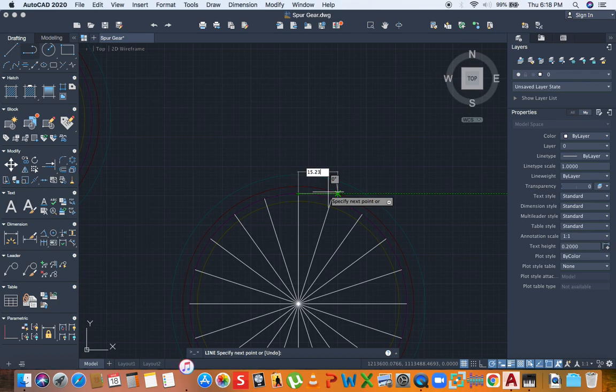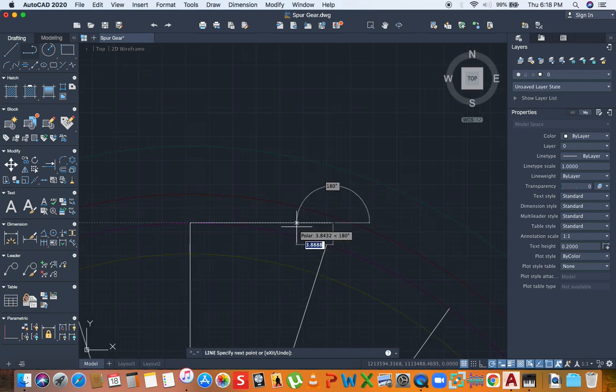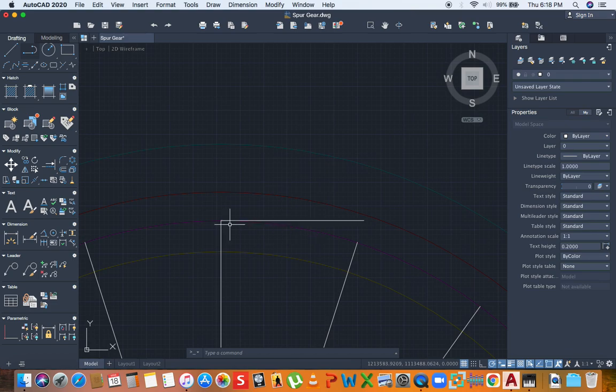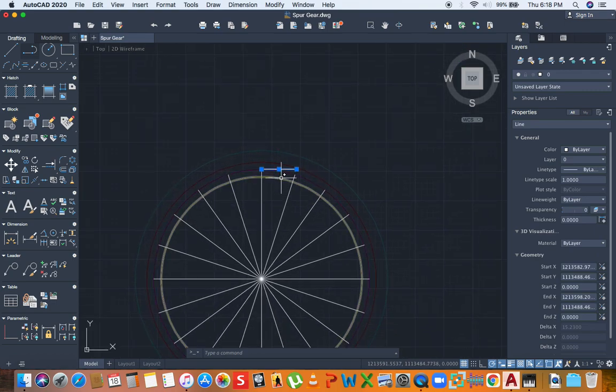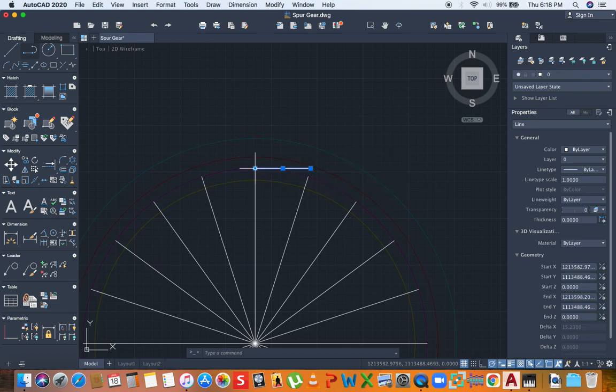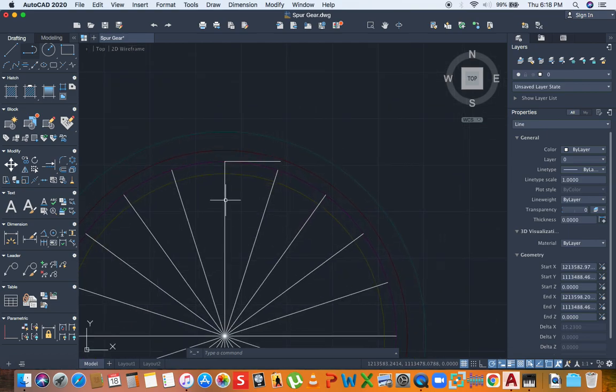15.23. I'm just remembering that the line seemed longer because it's straight, while this is a curve. Okay, so that settles it. This line seems longer than this arc, but it actually isn't, because this is a curve rather than a straight line. All right, so whatever this measurement is, this is perpendicular to this. There must be another line perpendicular to this with twice this measurement, then this one with thrice the measurement, and this one with 4 times the measurement, 5 times the measurement. That's how we construct an involute.